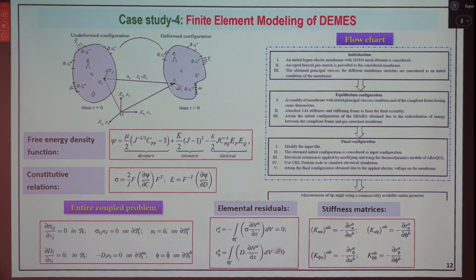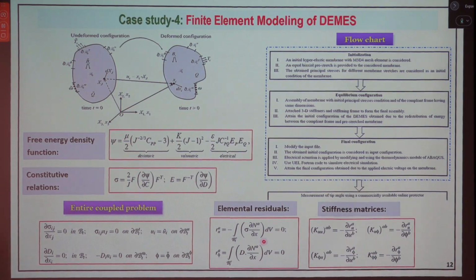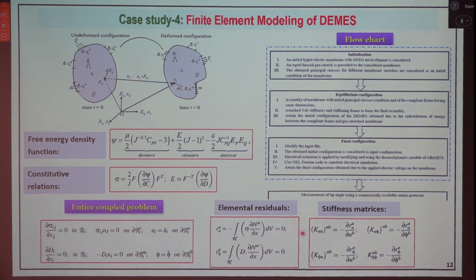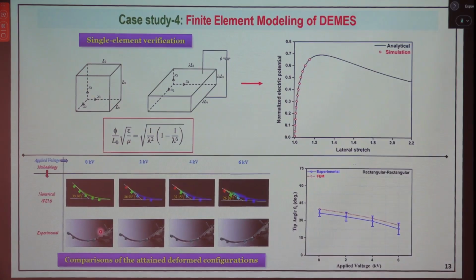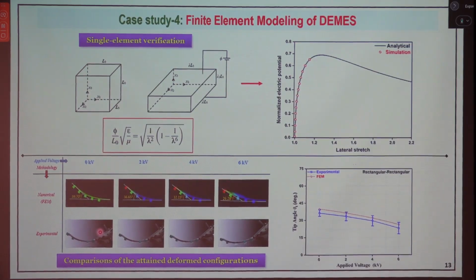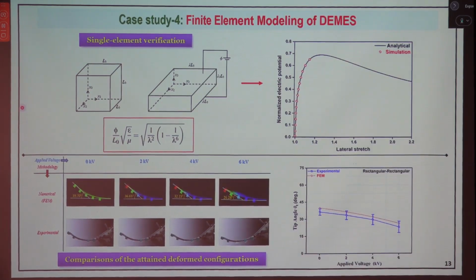Now you already know that we have the element level residual, and the Galerkin method can be implemented in FEM to solve these equations. Initially we validate with a single element. We have developed a user defined element subroutine in Abaqus, and we validate it for a single element.